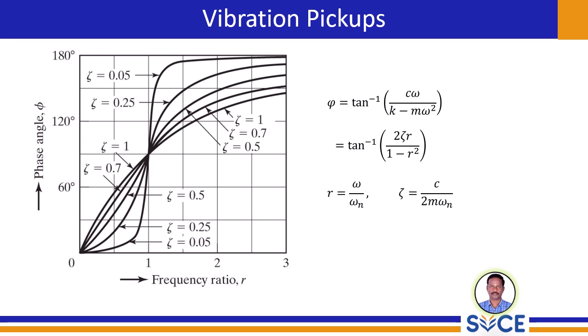Alright, we have looked at the amplitude response of our seismic instrument. Let's turn our attention to the phase relationship between the input motion and output relative displacement. As we mentioned earlier, in the steady state solution, the relative displacement Z is proportional to sine of omega t minus phi. That phi here represents the phase angle, indicating the time lag between input vibration and the resulting relative motion.